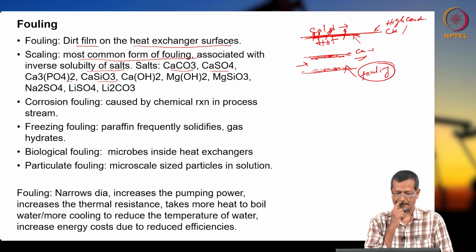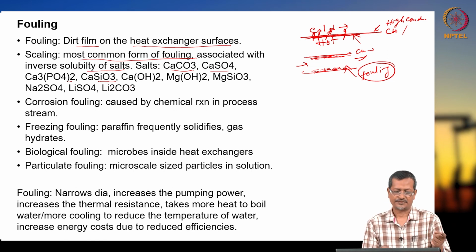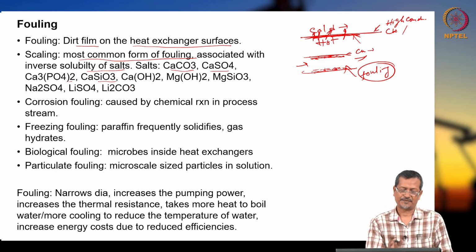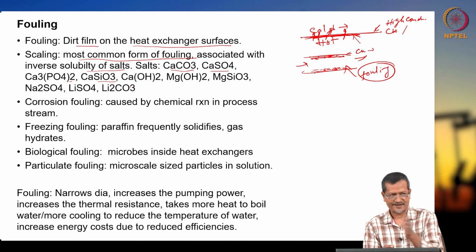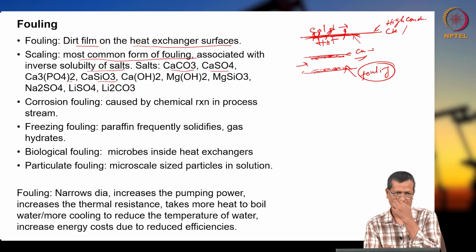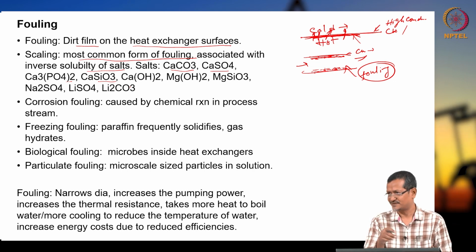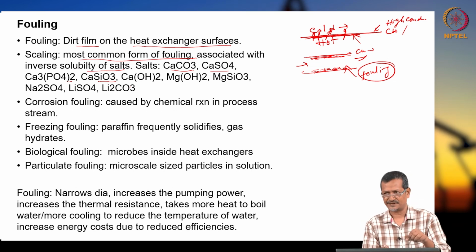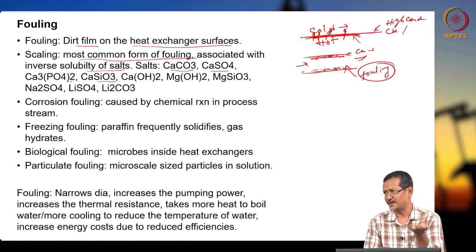Okay. So whenever you are using a high pressure system, you will have a pressure sensor and temperature sensor anyway. But in many cases sensor failure may occur, so an accident can happen. Before that, as a precaution, you remove all the salt and dirt and then use the water. Okay. But in an oil wellbore, whatever oil you are getting, you may not be able to do that. So in that case you have to observe whether salt deposition is happening or hydrate formation is happening. If hydrate formation is happening, then you have to remove the cause, or you have to use a line heater, so increase the temperature above the hydrate formation temperature, right?